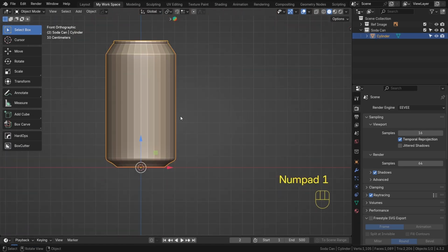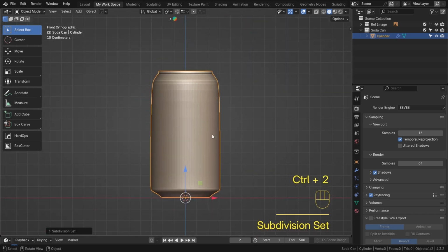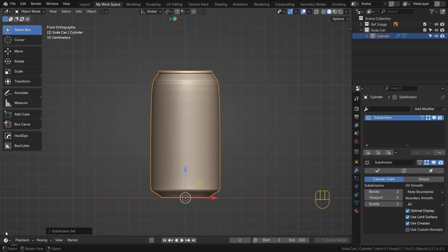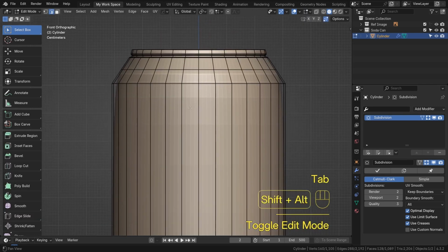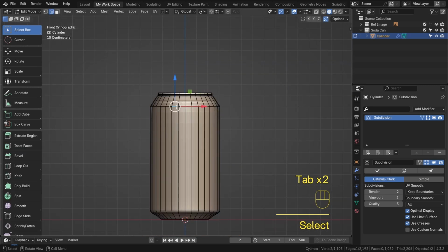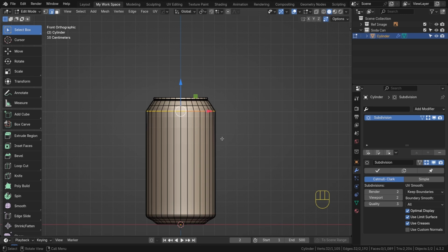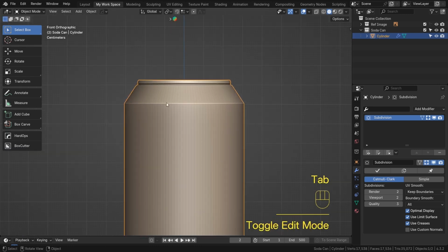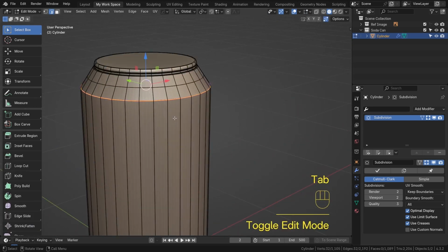And when we apply a subdivision surface modifier to see how it's working, you can see I have applied subdivision surface with a value of 2. Okay, so it's looking like that. So now you can see we have to make these sharp edges here. Yeah, you can add crease also by pressing Shift E like that. Yeah, so it will remain sharp while applying subdivision surface. Yeah, that color is changed.